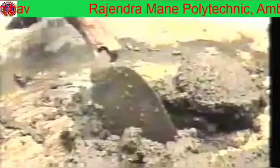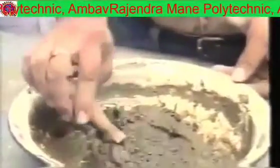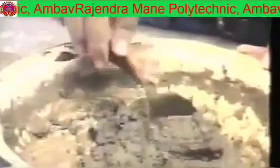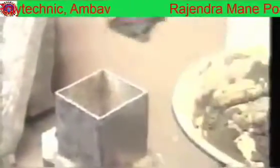This process of adding water and mixing to get the uniform paste should be completed within 4 minutes from the addition of water to the cement, and this should be conducted at 27 degrees centigrade temperature.